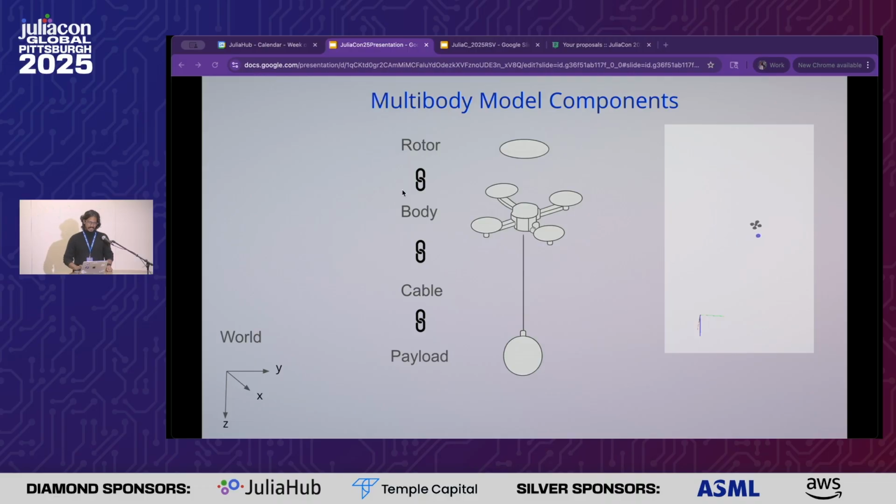So in this case, I've leveraged the payload position and orientation within the framework of the geometric controller, taking into account the physics that is required and what the quad needs to do to stabilize it. And yeah, the geometric controller used is an incremental update. It's not exactly the same as what it was, but it gets the job done.